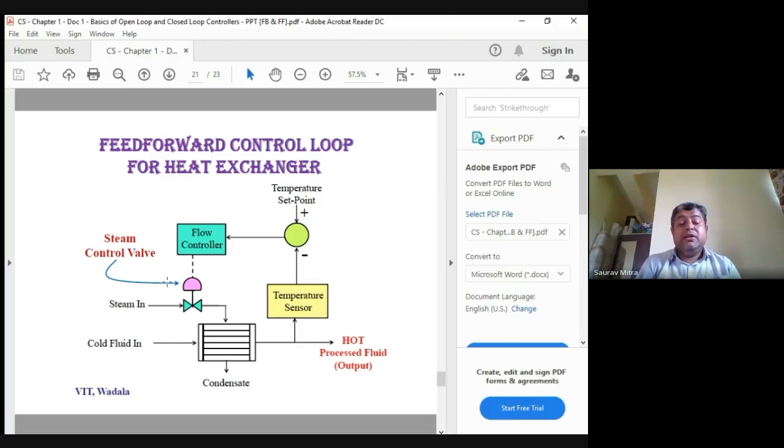But in cold time we know that the water will be very cold, and we don't wait for the water to fall on our body and give us a chill. So as soon as we enter the bathroom, we start the heater, and the water gets heated up and then falls on our body. So this is called a feed forward control system. We do not want the disturbance to affect us and then start the control system. As soon as the process starts, the control action starts.